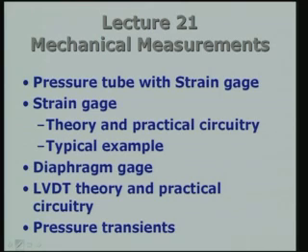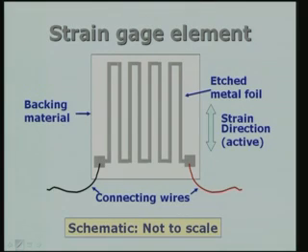So, if we look at the next slide, I have in fact shown a strain gauge element. It consists of, as you can see here, the wavy line. The wavy line happens to be a material which is deposited or etched on a metal foil. Etched means the rest of the material is removed and only this amount of material which is shown here in the form of a zigzag is going to be present. And you see that it consists of sectors which are straight, and then there is a small bridge between the two straight segments, again another straight segment, and so on.